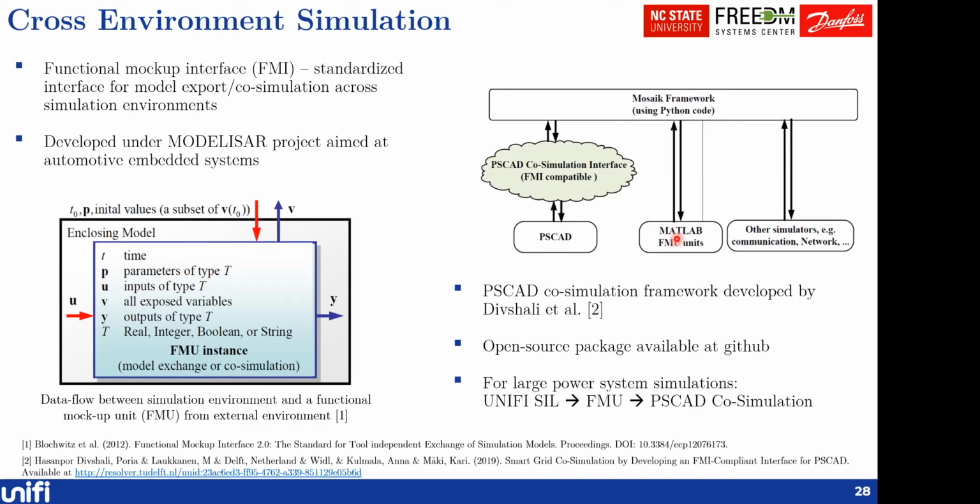And the nice thing about this is that it does not only need to be from MATLAB. You can have these FMUs that can come from other simulation environments as well, and they can basically link it with PSCAD. But one thing is that PSCAD already has a way to do co-simulation with MATLAB, but my understanding is that that can become pretty slow if you are trying to do data exchange at a very high rate.